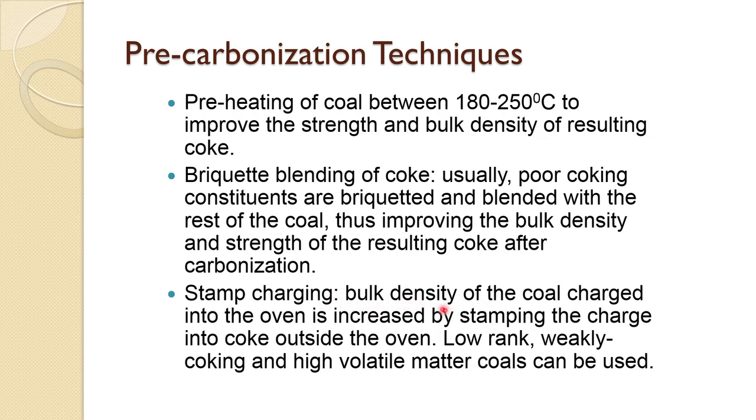So, in stamp charging, the bulk density of the coal charge into the oven is increased by stamping the charge outside the oven. So, what you do, you take a coal, you stamp it outside the oven actually, and once this is ready, then you dump it in the oven. So, these all are done outside the oven.